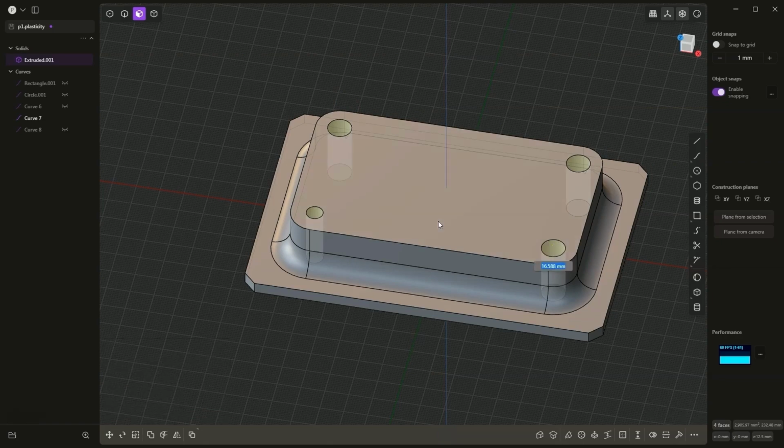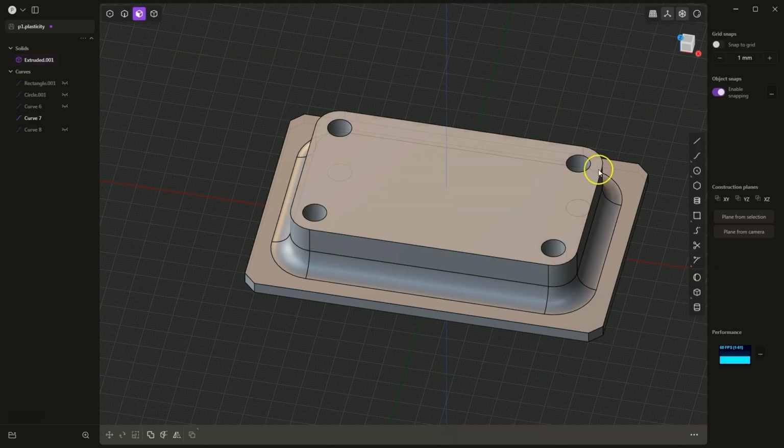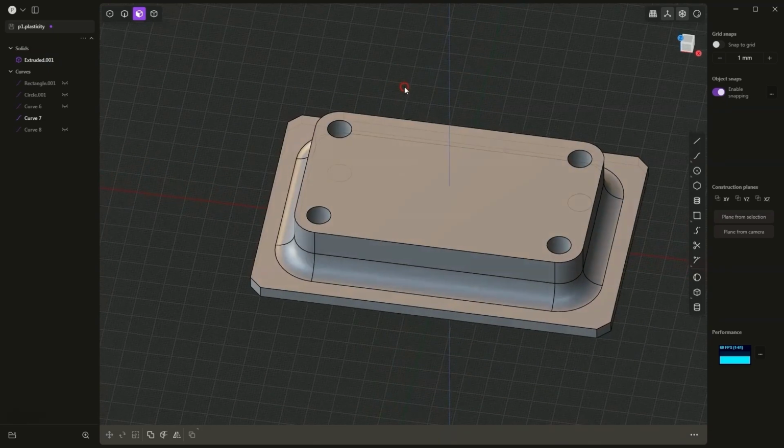Here we type, for example, 7, enter, and the diameter of all holes has been changed. Here I will revert to a value of 10 millimeters, so all holes are selected. I press the equal sign, type 10, hit enter, enter again, and we returned to holes with a diameter of 10 millimeters. Now in these holes, we will create counterbore holes.